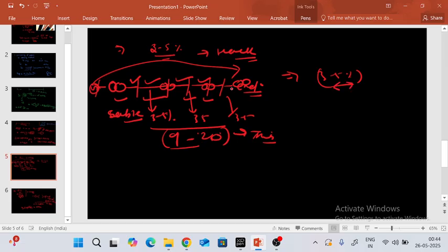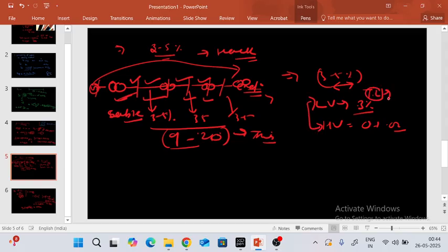For example, in the distribution LV system, 0.3% loss is acceptable. For the HV side, 0.1 to 0.2% loss is acceptable. It totally depends on your transmission lines and the particular cables you are using. Okay guys, hope you understand these fundamentals.